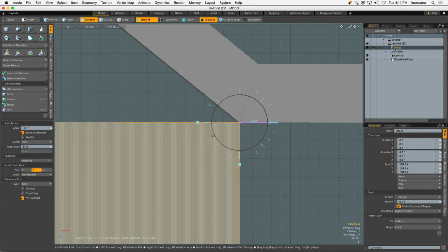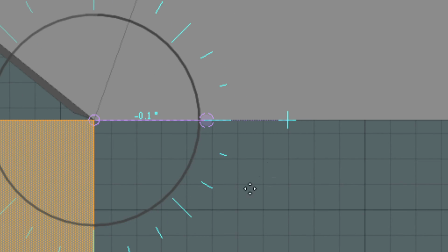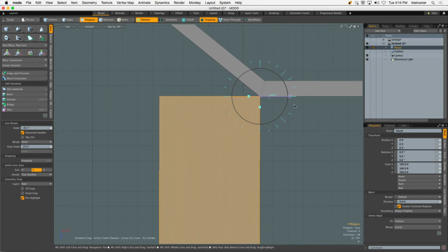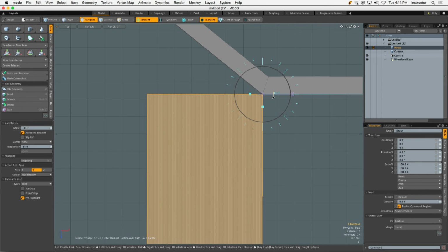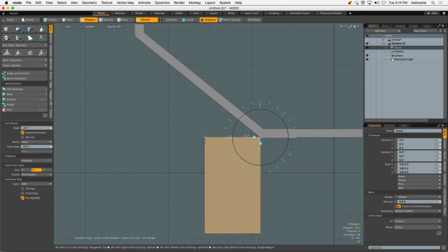And there's two really important interface elements inside of here. If you look carefully, because I'm all zoomed in, it's going crazy, we have this little cross. Then we have this purple handle with a little widget on it, okay? That little cross is important. We want to place that cross at what I would call the starting angle. So I want to place it on that corner right there. See how it snaps? Boom. We're establishing the start angle of our rotate operator.